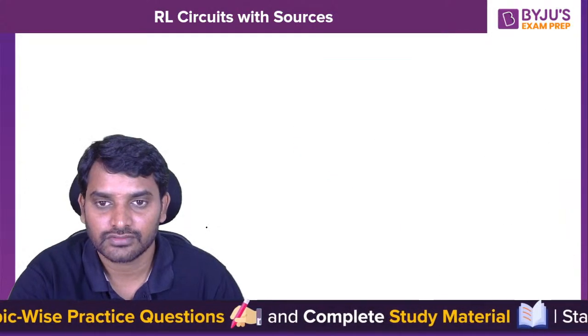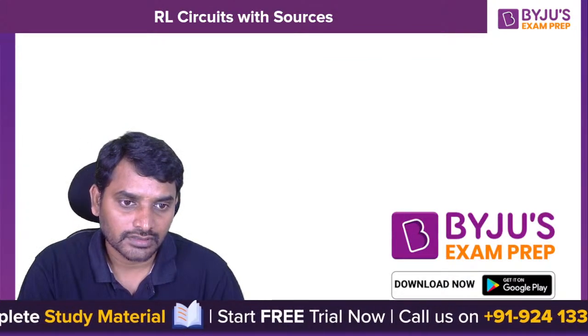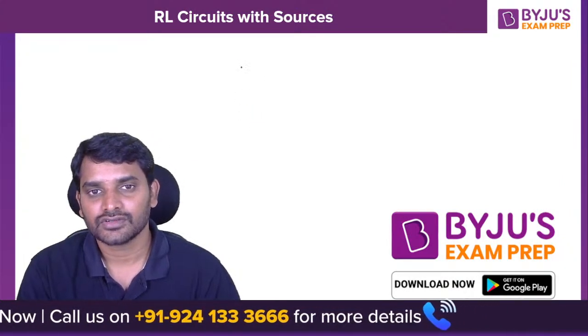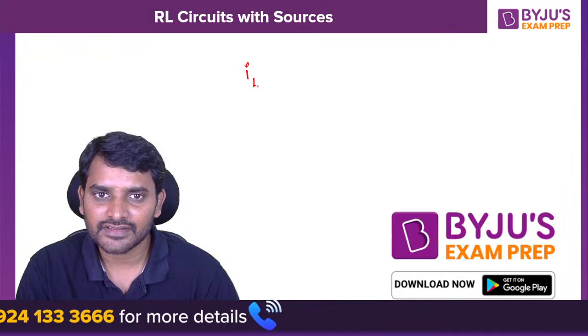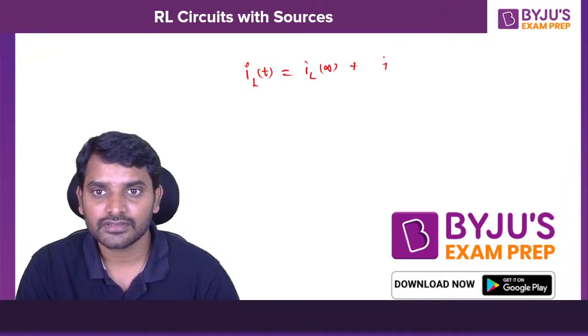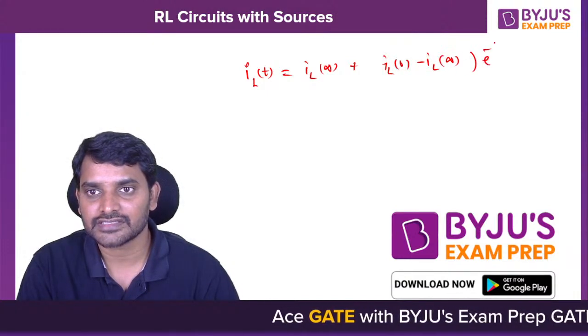So this is how we take up RL networks with sources. Whether it is with sources or without sources, this equation you need to remember: final value plus initial value minus final value into e power minus t by tau.